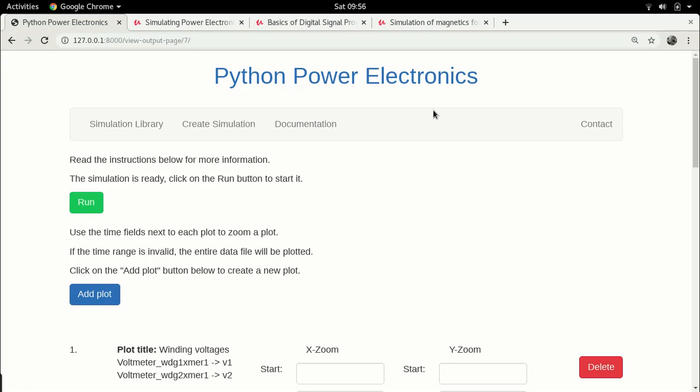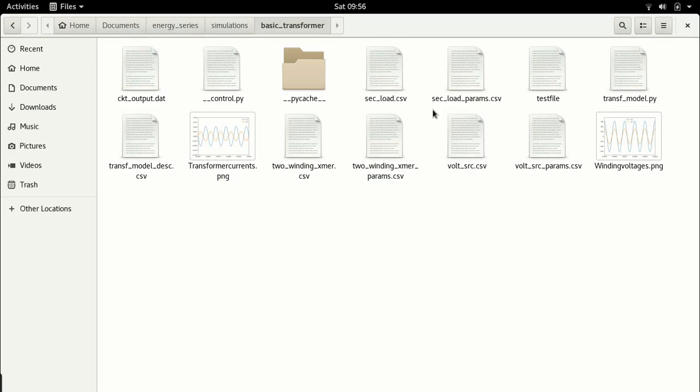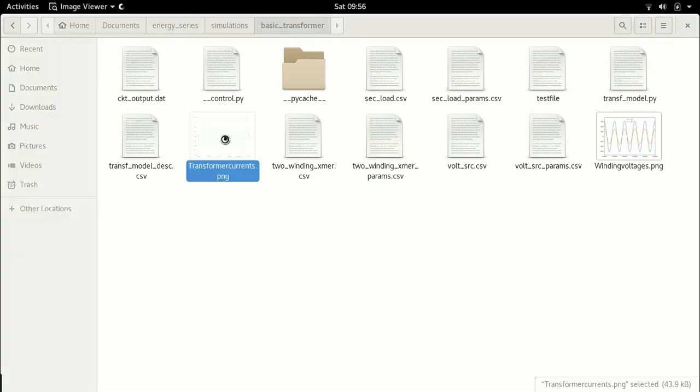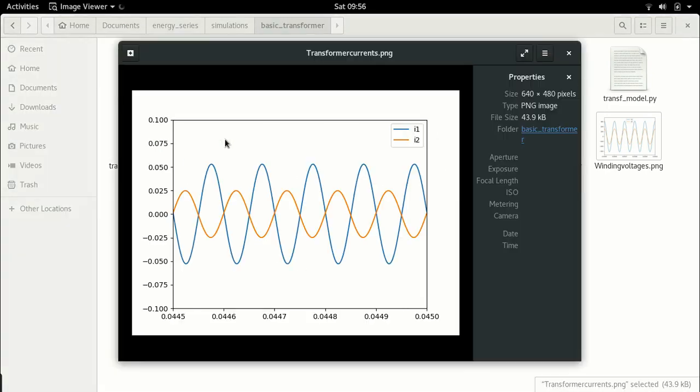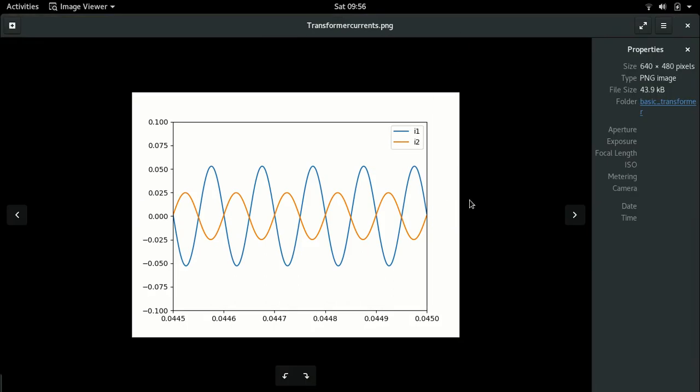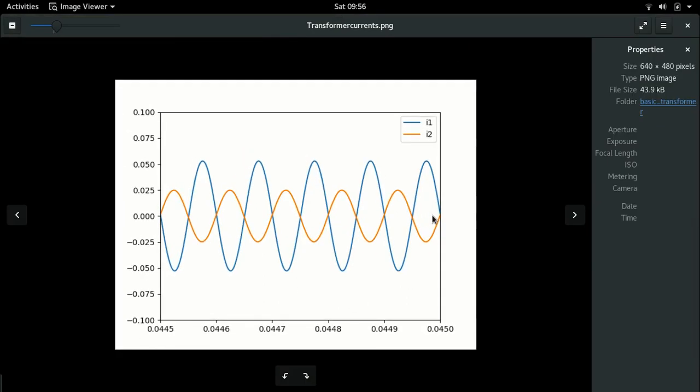So hello everyone and welcome to this next lecture in the DC-DC converter series, and we will continue with simulating the transformer. Where we had left off in the previous lecture was we had simulated a high frequency transformer, that is a 5000 Hertz transformer, but we had kept all the simulation parameters the same, which means we had kept the integration time step the same, the control sampling time step the same, so everything was the same except that now we were simulating a high frequency transformer.